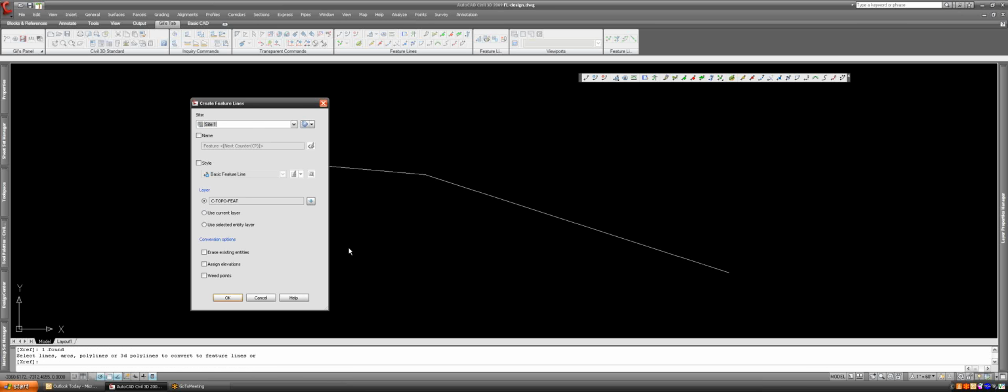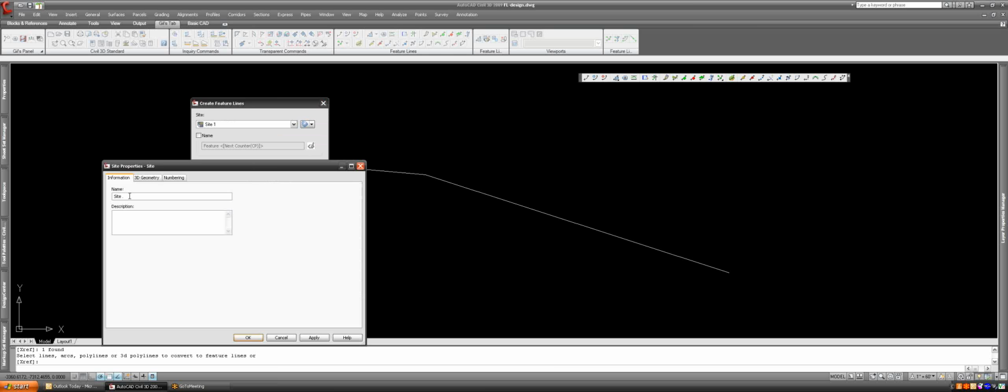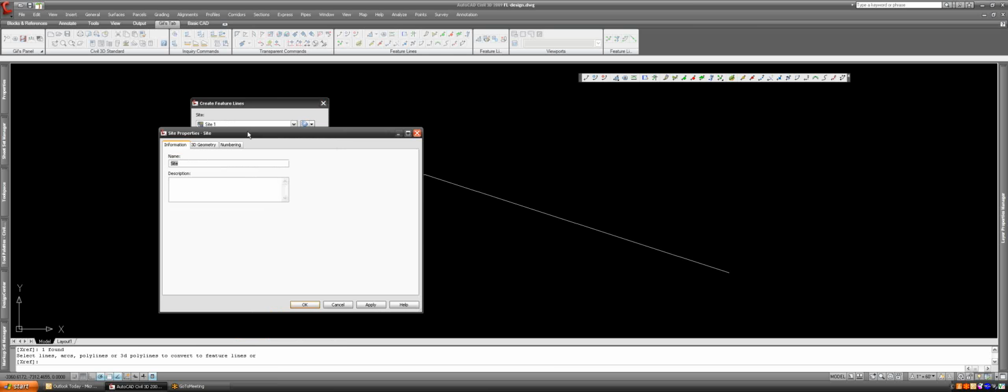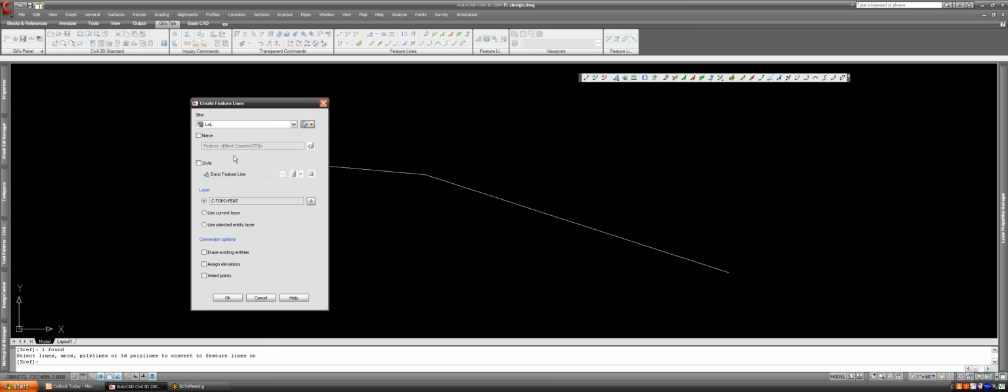Once you do that, press enter and give it a site. We're actually going to create a new site, and we're just going to call this Lunch and Learn for today. Usually when I create a feature line, I keep the names normal. Usually there are not so many feature lines in a site, but sometimes it's a lot easier to give it a name.